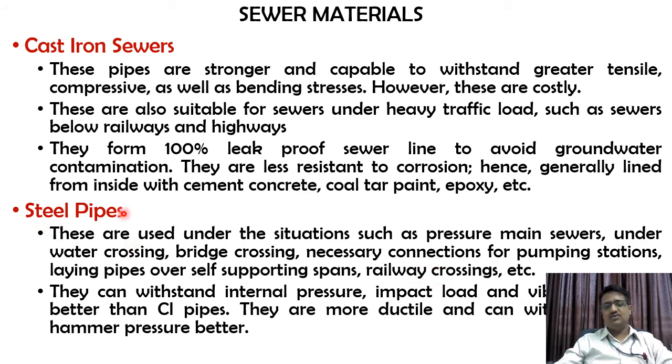So already you know steel, right? Steel is a much advanced version of your iron. It can have its molecular structure customized based on the requirement. So the amount of compressive as well as tensile strength that it can hold, even the durability, will be much more than the cast iron we have seen above. So even though this steel pipe will be costly, these can be used for those particular conditions where you require quite a strong material for the sewer.